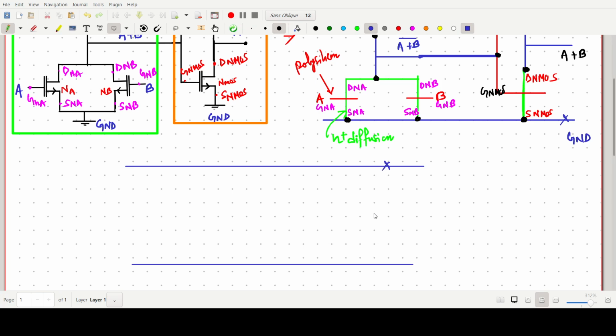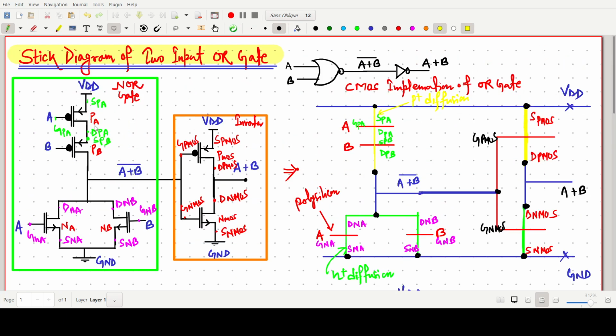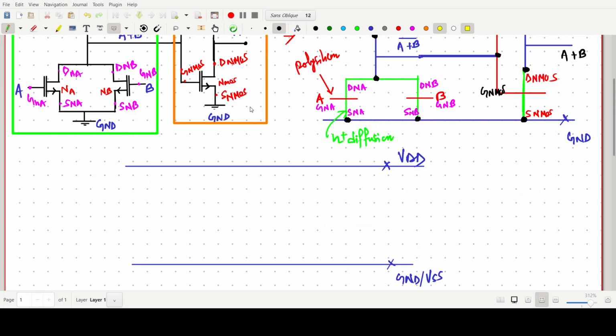Okay, one is our VDD with supply and ground, or VSS should be the blue color. Then after, see, this one is our two PMOS. Two PMOS are connected together. So one yellow line we have to make. So two transistors are there. Then after two NMOS is there in the below, and these NMOS in parallel kind. So I am making like this. Then two polysilicon lines.